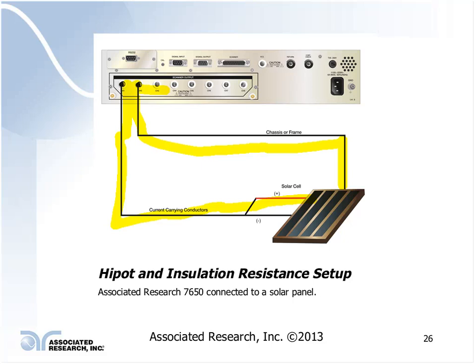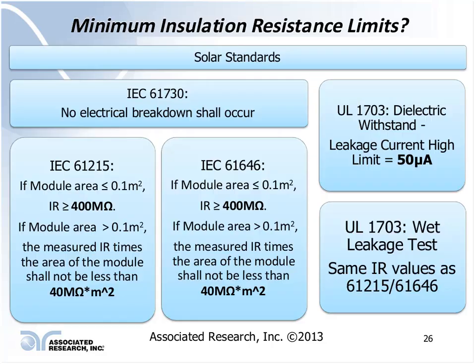So really no different than the last diagram we looked at. In this case, I just used a multiplexer, so if I'm on a production floor and I need to run my test in both polarities, which you do, I can do this in an automated sense so that the operator doesn't have to go changing settings or clipping leads in different spots between each of these tests. It kind of takes out the human element too, in the event that somebody might screw it up and not clip on a proper return point or might not get a good connection. This kind of takes that out of the equation.